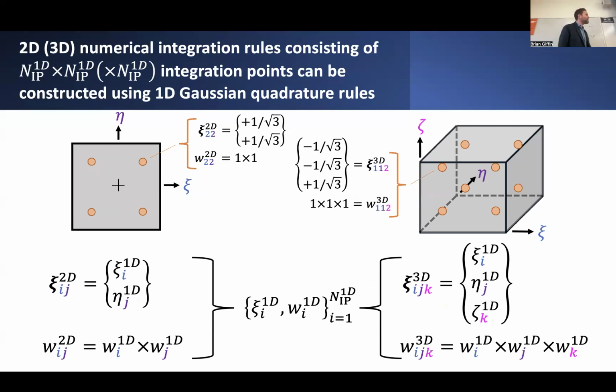So the basic idea is you can use these basic 1-dimensional integration rules as we've previously constructed, the same Gaussian integration formulas that we developed previously, and then just define the integration points for this 2-dimensional or 3-dimensional domain, with the product of all of the integration weights giving the corresponding weights in the 2-dimensional or 3-dimensional case. And then the actual coordinates of the c, eta, and possibly zeta components just independently range over those different values as you would have previously defined.